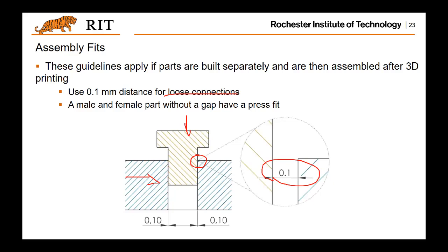And that works for a male and a female part without a gap. If that's the case, that means you are designing a press fit. You need to apply force when you want to assemble them together. If that's the case, then there's no need for a gap. Otherwise, you want to have a gap for looser connections.